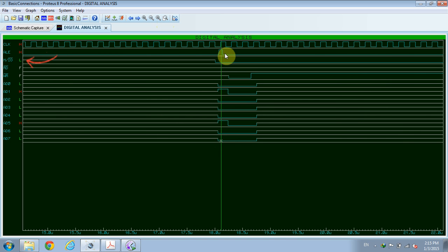The memory I/O signal is always active low, as the instruction is accessing an I/O port rather than a memory location. The read signal is always floating, as the instruction is not reading data from the bus. The write signal is active low from T2 to T4, as the instruction is writing data to the bus.